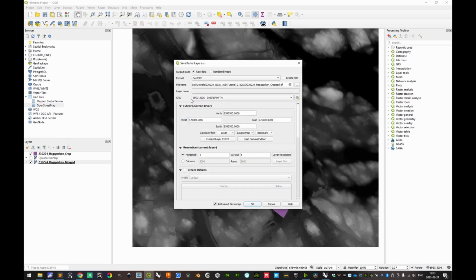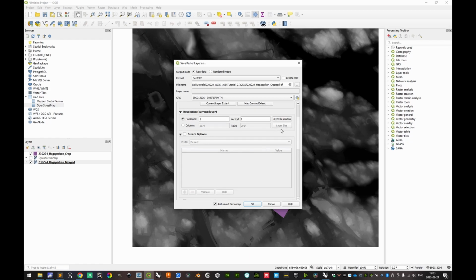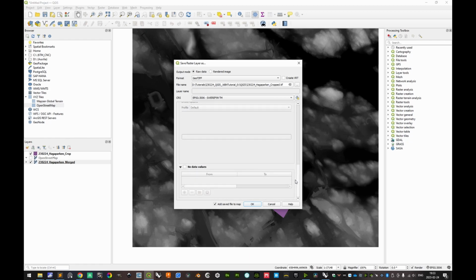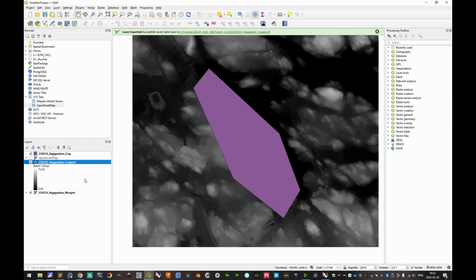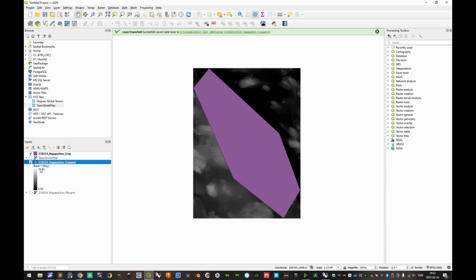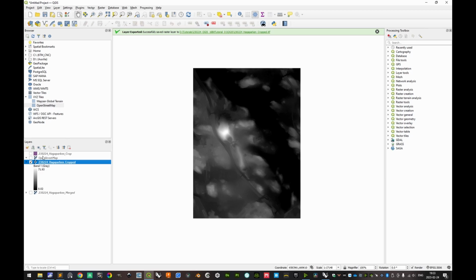All right, it's in the coordinate reference system of our choice, and the crop should be from the crop layer. Let's make sure that the left hits the ceiling of 2, the top hits the ceiling of 8, the right is lowered to the floor of 8, and the bottom is lowered to the floor of 4. Very good. One pixel resolution per meter, and let's make sure that we have this as a file. Very good, and okay. Right, we have our crop. We can disable that crop there.